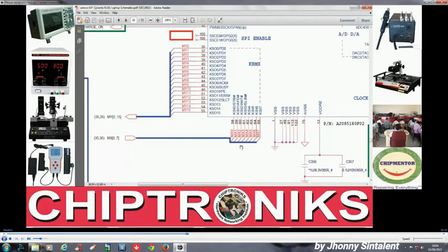But in the case of a desktop keyboard, you have two interfaces. One is PS2, another is USB. So for each key you get a scan in and scan out. Two codes are generated when you press any key: one is scan in and one is scan out, and that data is transmitted by the keyboard encoder via PS2 or via USB to the keyboard controller, right?